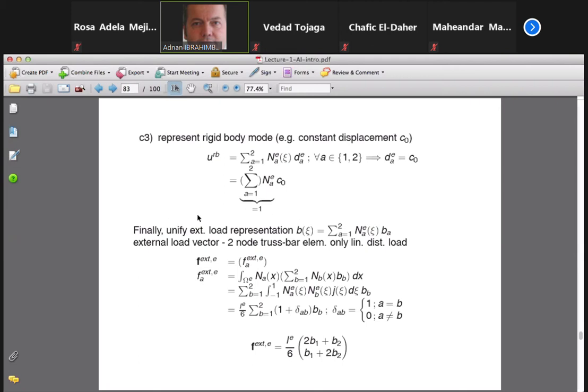Now, if you have a finite element technology, computer software, you also need to represent the loading. So this is not really a crucial requirement. This is more like a convenient requirement. But for many codes, the external loading is also represented by using the same shape functions as those that you have using displacement. There's really nothing fundamental there, except for convenience, because these are shape functions which are already available. So why not use them to obtain the corresponding external load?